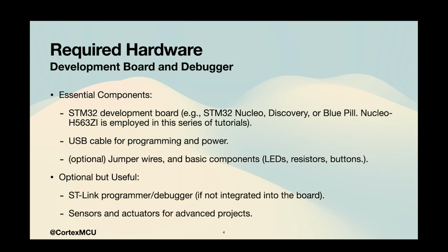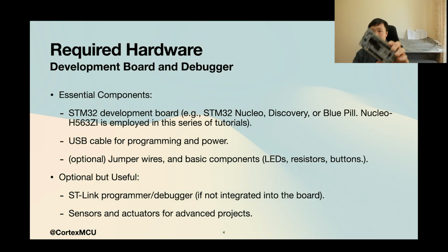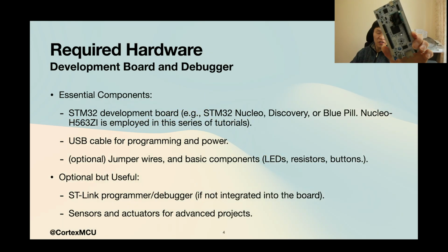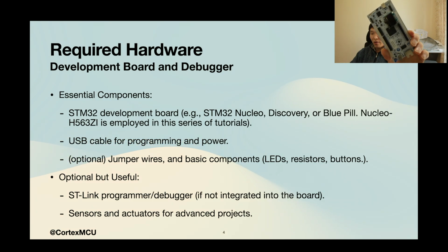Next one is optional but useful: an ST-Link programmer and debugger, which is not integrated into some boards. By the way, if we use the Nucleo board, there is a built-in ST-Link programmer and debugger.